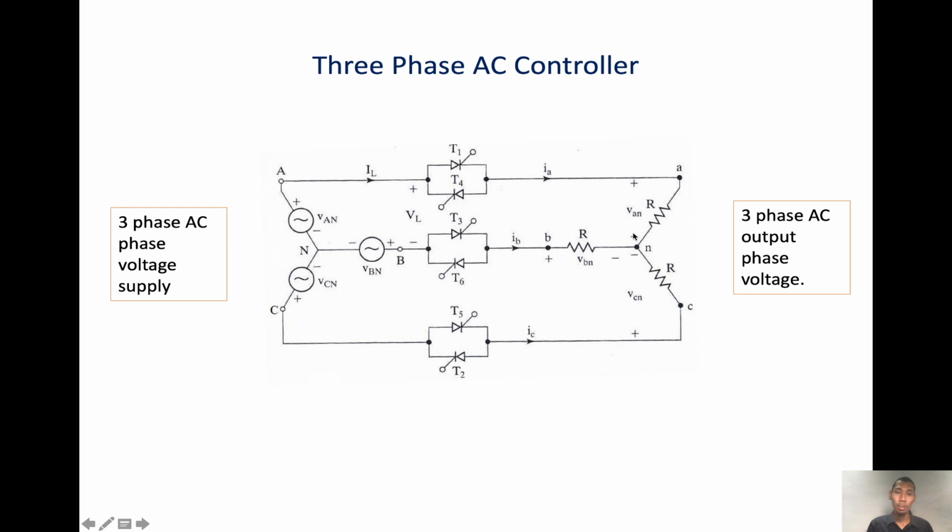Looking at this circuit, the input will be identical to the output when we use a diode or the firing angle is 0. There is no change. All the input power goes through to the output. As the firing angle increases, we see a decrease in the magnitude of the output voltage across the load.